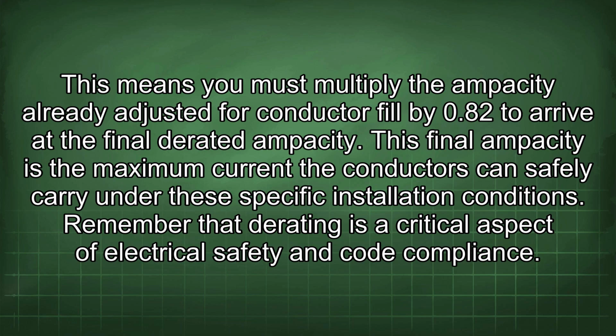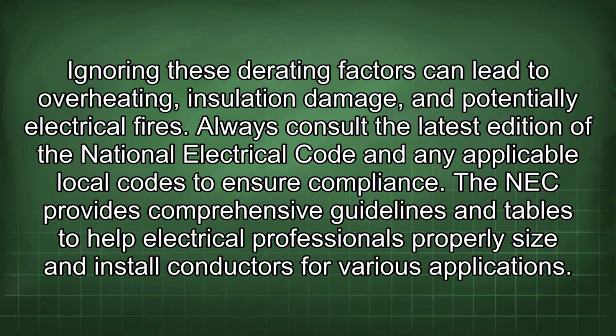Remember that derating is a critical aspect of electrical safety and code compliance. Ignoring these derating factors can lead to overheating, insulation damage, and potentially electrical fires. Always consult the latest edition of the National Electrical Code and any applicable local codes to ensure compliance. The NEC provides comprehensive guidelines and tables to help electrical professionals properly size and install conductors for various applications.